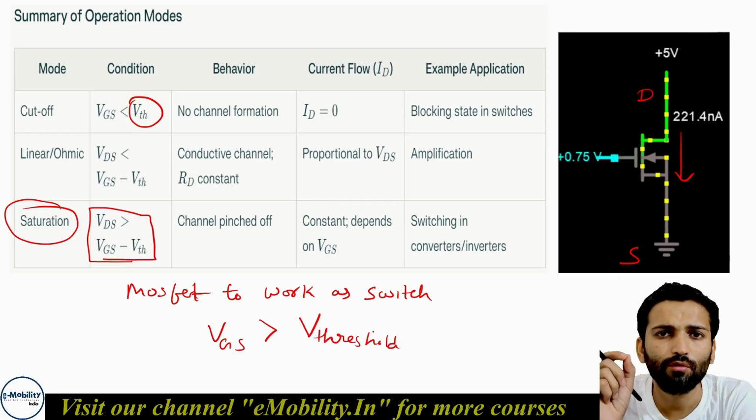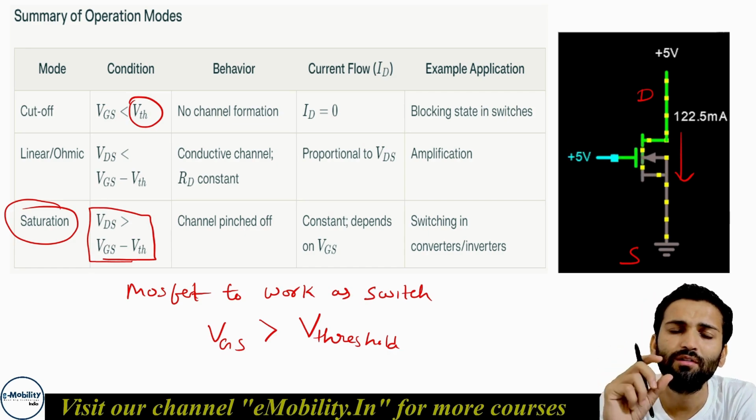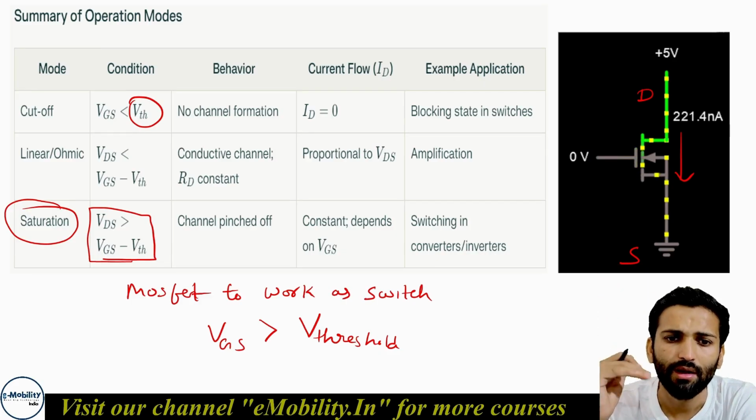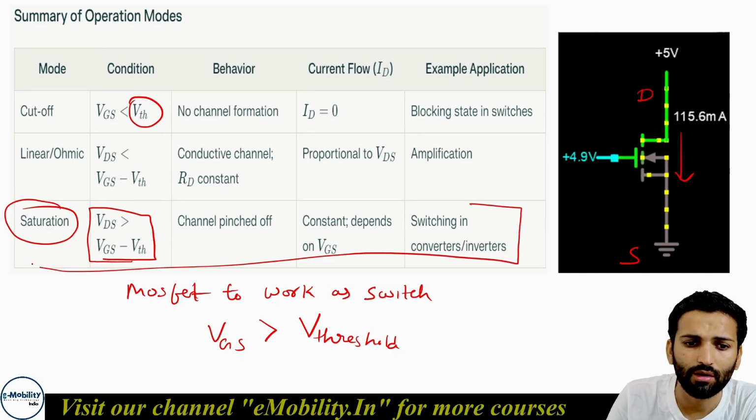And for most of the MOSFETs which I will be showing you through the LTspice model, we will be using a 12 volt gate drive. So the threshold will be somewhere around, say, 6 or 7 volt. So we'll be breaching that threshold level and we'll be switching the MOSFET on. So we'll be working as here only.